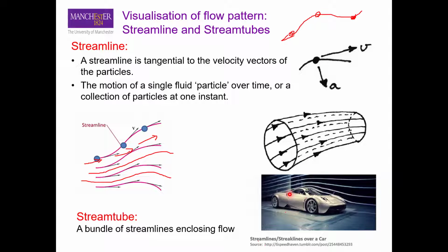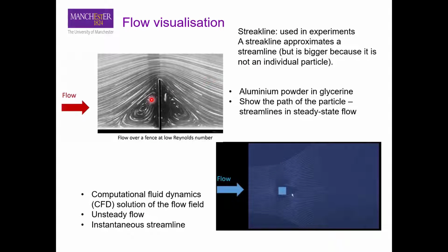And here there is another example. So here, for example, you have a fluid that is moving in this direction, and then you have this, for example, a column as a resistance. So this fluid is a mixture of aluminium powder and glycerin, and the lines that you can see are the lines formed by aluminium powder as it flows through this system, okay? So here you can say all the lines are straight, that show you that you have a uniform region. It means that the velocity is not changing.